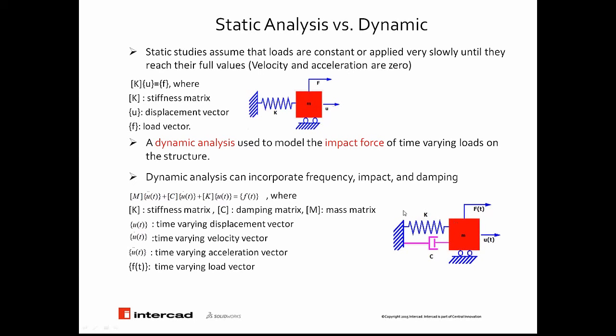If you look at the figure, we have the same system, with a damper, K, and force and displacement varying with time. So in any dynamic analysis, force is time dependent, therefore displacements are time dependent as well.